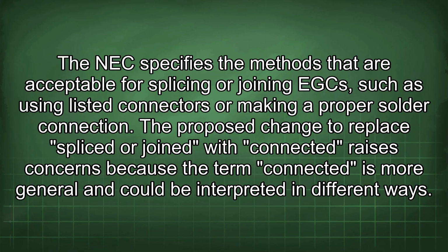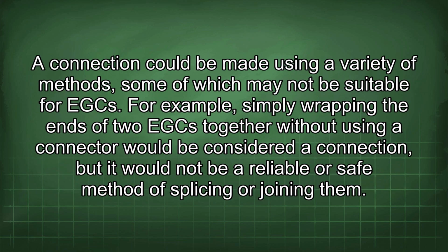The NEC specifies the methods that are acceptable for splicing or joining EGCs, such as using listed connectors or making a proper solder connection. The proposed change to replace spliced or joined with connected raises concerns because the term connected is more general and could be interpreted in different ways. A connection could be made using a variety of methods, some of which may not be suitable for EGCs.